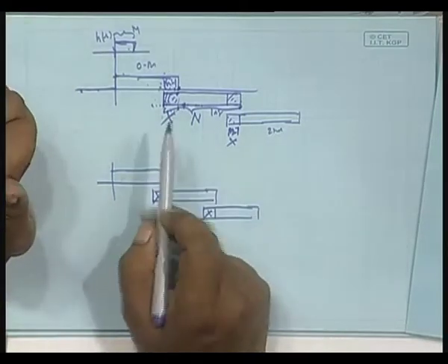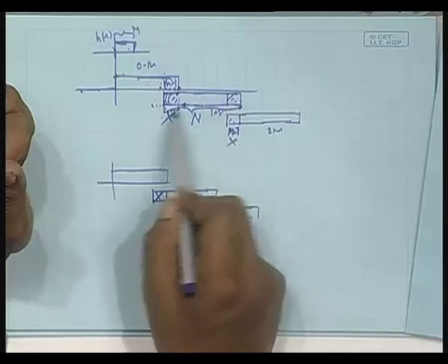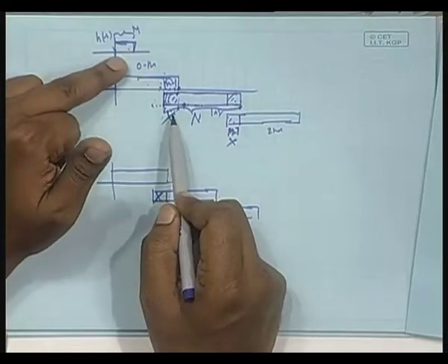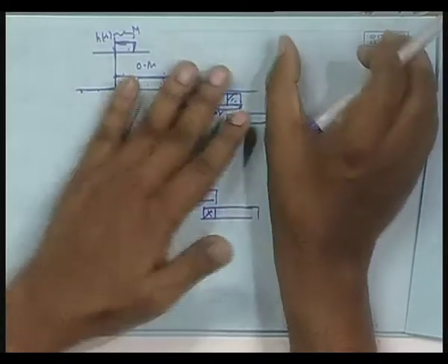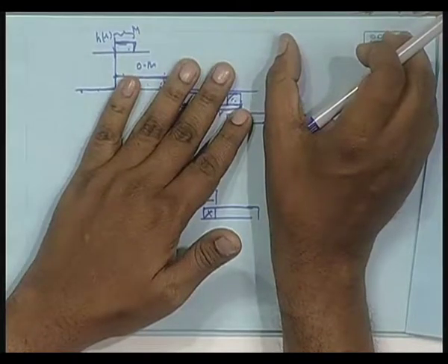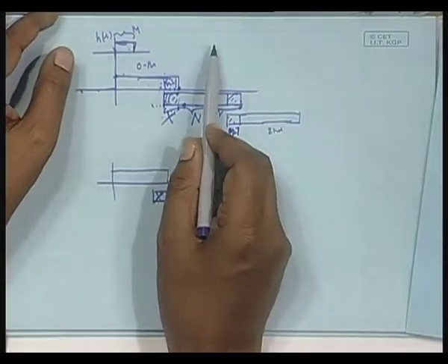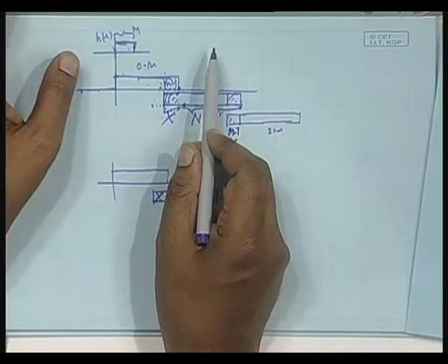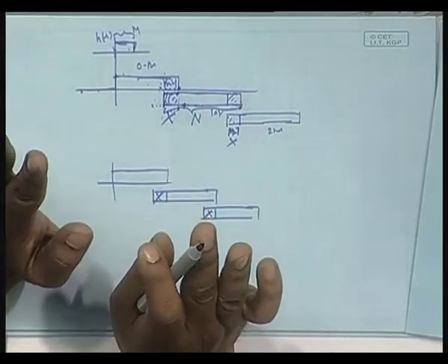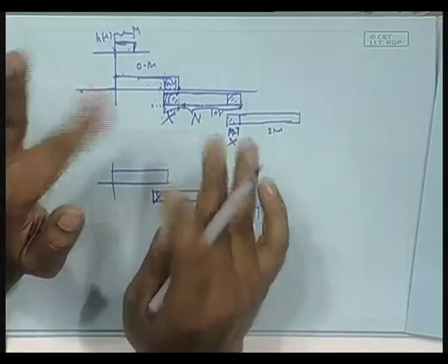So, you can tell me, fine, you want to do a linear convolution with this block of length capital N and a block of length m, you add m minus 1 zeros to this one, and n minus 1 zeros to the other. So, n plus m minus 1 is the length, and that will work. DFT, DFT, IDFT, you will get the full output, and there you throw away these samples.